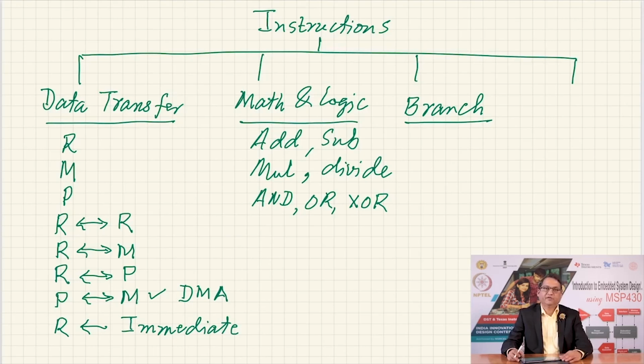So the instructions of such nature, where the control of the microprocessor is altered from the current location to a different location which is not necessarily sequential, are called branch instructions. What are the types of instructions? So you would like to jump to a particular location. You may want to jump without any condition, or you may want to involve a condition. Maybe there are things like flags in a microprocessor, so you would like to jump if a certain flag is set, or you may want to jump to a location if this flag is reset.